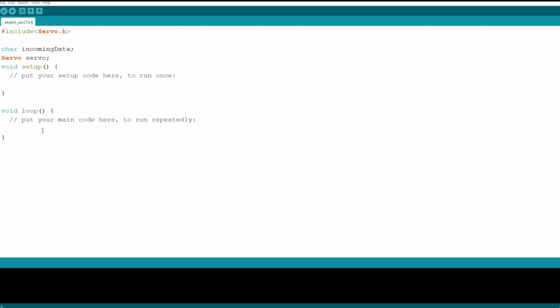As you know, if you want to do this operation, we need to move inside of our setup function. So let's delete this comment first. And also, let's call here our object. As you know, this is servo. And here we will use our attach method, because with this method, we will define our servo pin. As you know, our servo pin number is 9, so that's why I entered the value 9 in the parentheses and also put a semicolon.